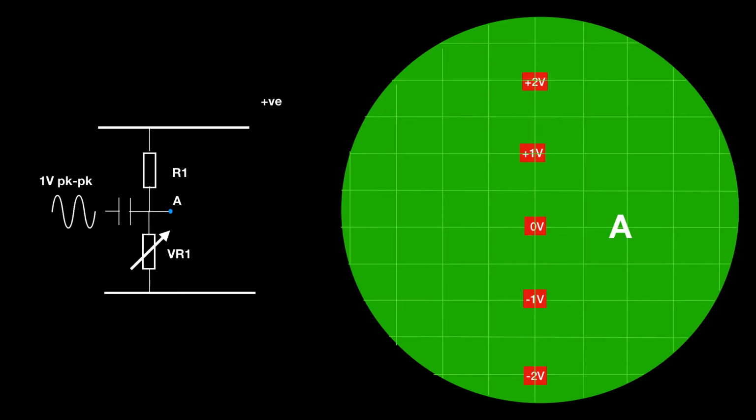Now, if you're unfamiliar with oscilloscopes, I would recommend you have a look on YouTube. There are plenty of videos there showing how to basically operate them. But what we have is essentially a screen, and a little dot will move from left to right across the screen, and at any instant the height of the dot above the 0 volt line will represent the voltage. If it's a positive voltage, the dot will be above the line. If it's a negative voltage, it'll be below the line.